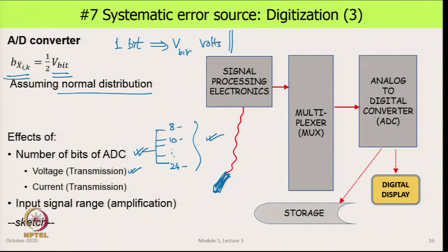In the laboratory, these could be quite a ways apart. In an industry, say like a petrochemical complex or a refinery, these could be hundreds of meters, if not thousands of meters. In a smaller thing like say a milk processing plant, this could be tens of meters. So, what happens? We have two options. The instrument can either output a voltage signal over a certain range, and this could be the analog signal, or we could even output a current signal.